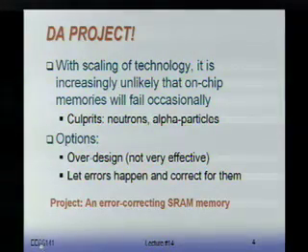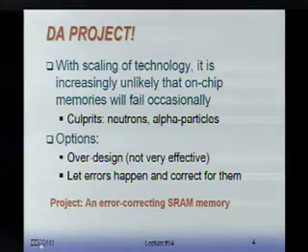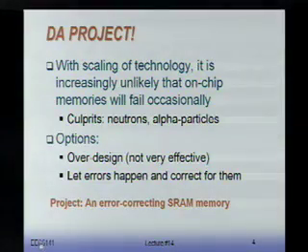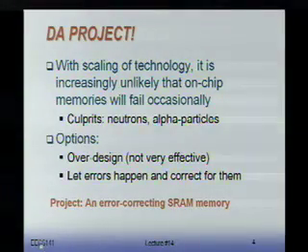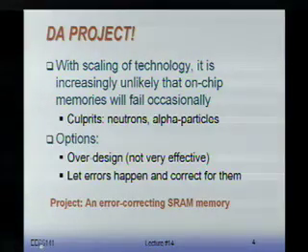There's a couple of reasons why that is. Obviously, there are some manufacturing problems. If I have 700 million transistors, there's a good chance that some transistors might be bad. Now, with memory, that's not too hard to deal with, because when you get your chip back from the fab, I can test it. And if there are certain areas that are corrupted, I can exclude them, like you do with a disk, for instance.